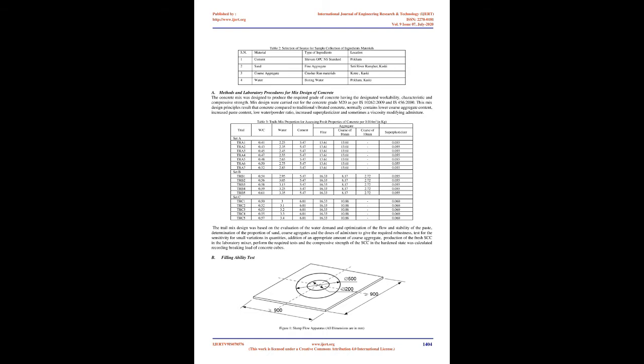Self-compacting concrete of required grade was formed through trials, and properties of fresh concrete were ascertained through slump flow test, L-box test, and V-funnel test. Concrete cubes were cast and curing was carried out. Compressive strength of cubes was found out and analysis of results was carried out. Proper mix for self-compacting concrete was adopted from trials for replacement of cement with rice husk ash.